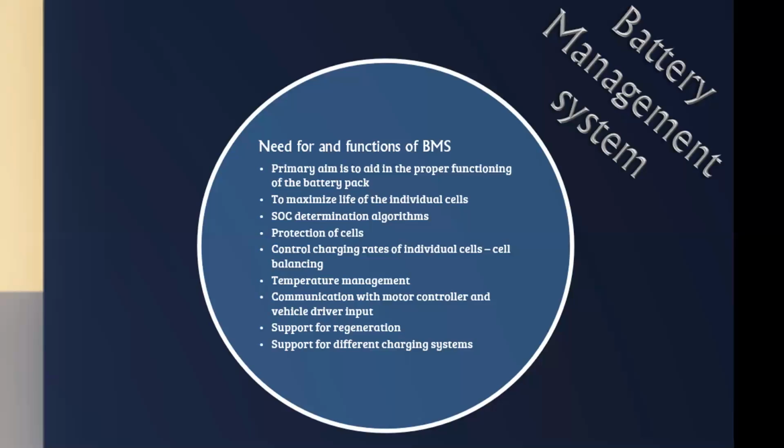Next is the SOC determination algorithm, because we have to know what is the level of the charge that is stored in the batteries. Different SOC algorithms exist, where the very common one is the Coulomb counting method. Such algorithms are also implemented in the battery management system itself, and that helps in understanding what is your charge state in your battery.